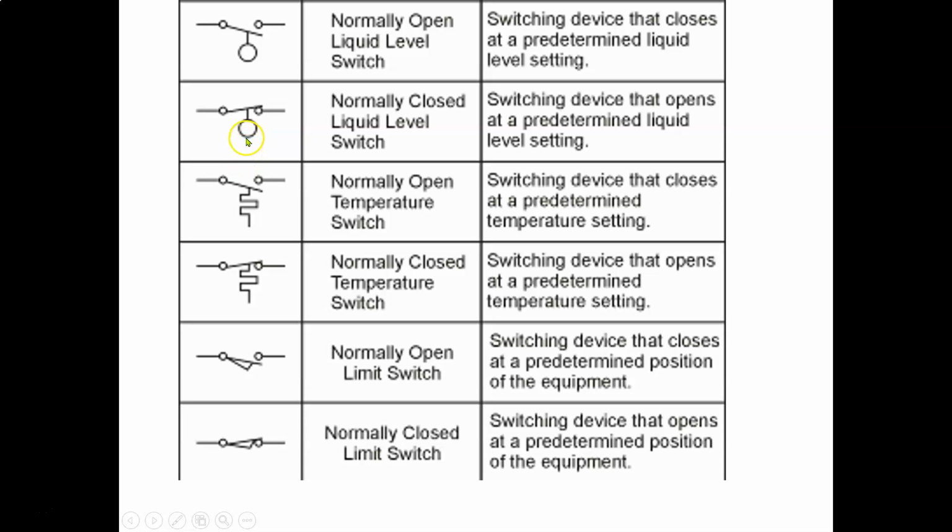So if the tank fills up, you want that motor to stop pumping water into the tank. It's going to push up and open a circuit here, cutting off the motor, cutting off the pump. Unlike this guy here, if the water gets too low, it's going to open up a switch here, signaling for your motors to turn on and start pumping water, etc.